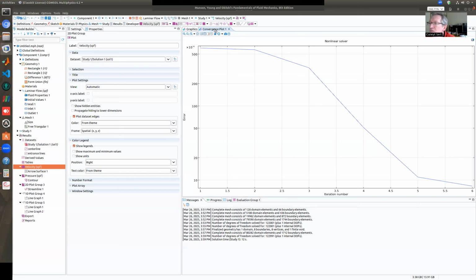And that happened. So we just demonstrated it, right? Most probably it was a mesh issue. Most probably I needed to create a more careful mesh, or maybe something else, but most probably mesh. But this one converged. I reduced the size of the obstacle, so it is blocking the flow less.